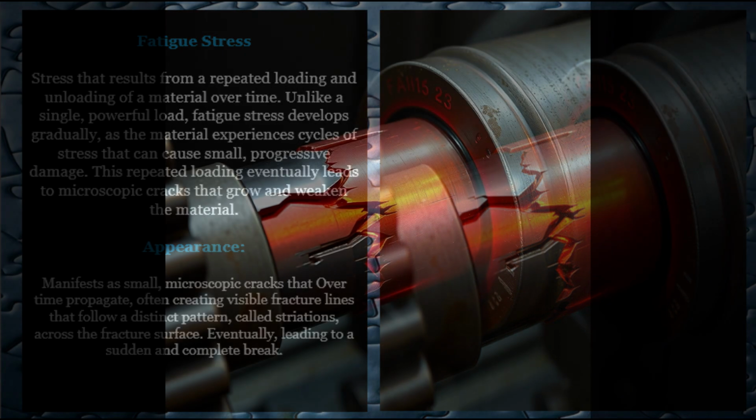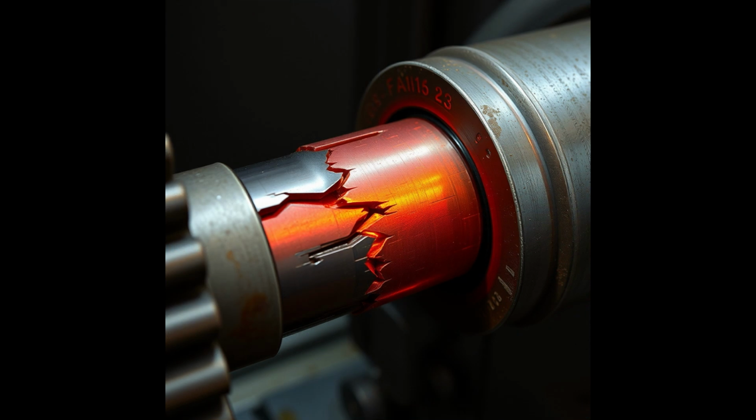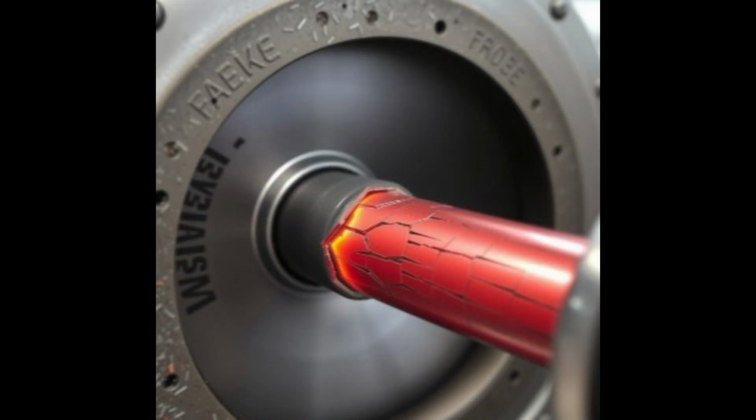Appearance. Fatigue stress manifests as small, microscopic cracks that usually start at points of high stress concentration, such as edges, corners, or surface imperfections. Over time, these cracks propagate, often creating visible fracture lines that follow a distinct pattern called striations across the fracture surface. Eventually, the material reaches a point where it can no longer sustain the stress, leading to a sudden and complete break, even under relatively low loads.